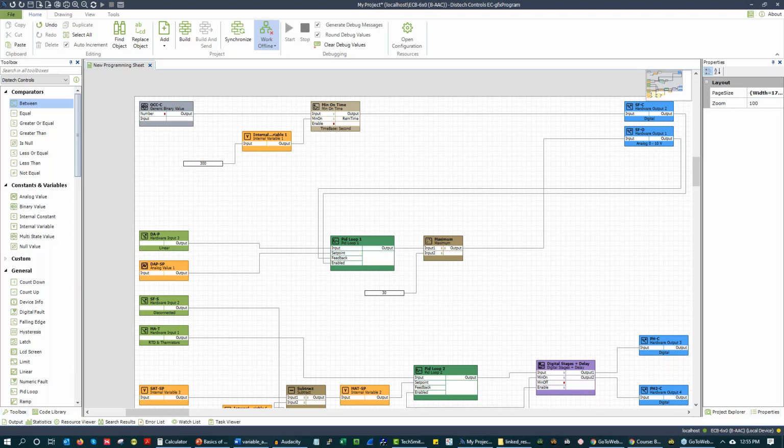So how do I implement controller watchdog logic? When the controller goes offline from a supervisory controller, it goes into a safe operational state. So you would have a heartbeat. It would be a network variable, and you would then have switches that switch based on the heartbeat. So I would create a network variable, and if I lost status, if that network variable went false, then it would switch states. So there's that.